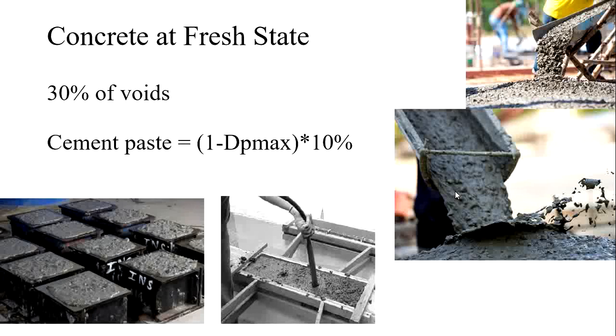So, in order to make a perfect mold, or a concrete in a perfect cube, we will be using the needle vibrator or vibrating machine. Initially, when you insert the vibrating machine inside the mold, the voids present between the coarse aggregates, the fine aggregate and the cementitious material get reduced.